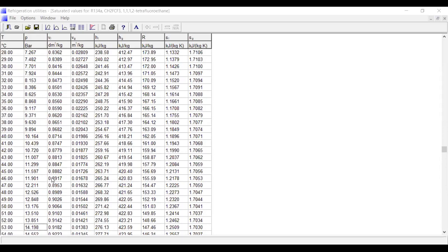Okay. So initially in liquid form, when you suck it, it turns into low pressure and then low temperature, and also part turns into vapor, so vapor and liquid become two phase. So for different substances, the cooling substances, for different pressure reductions, there could be different temperatures.